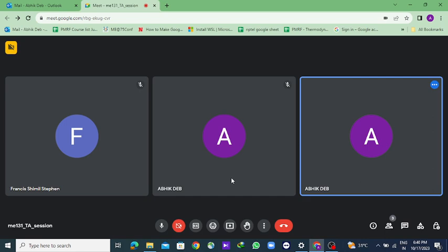In the P.N. Rao book, they have given a table for different metals and shrinkage. They have just given shrinkage, so we can consider it as solid shrinkage. If it is termed just shrinkage, then we can consider it as total shrinkage or only the pattern shrinkage. The shrinkage allowance is given to shrink to room temperature. Let me first clear it out.